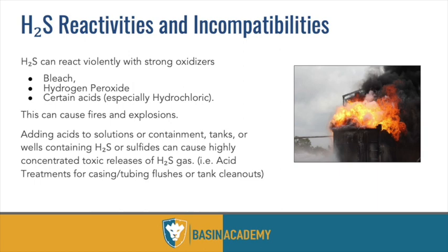So again, that's where we have chlorine and hydrogen. And when you think of saltwater disposal, it's a lot of salt water, right? And salt water and hydrogen mixing together with certain acids, it's going to bond together and either release H2S or even potentially form H2S. So during acid jobs on saltwater disposals, that's another place you want to be extremely careful. This will cause fires and explosions.